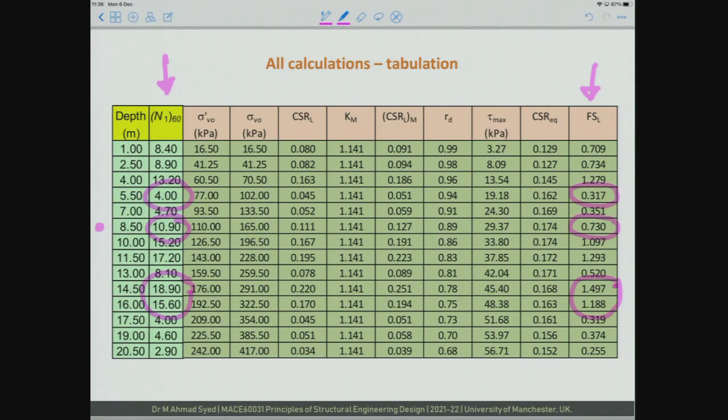So you have a higher resistance against liquefaction for relatively higher N values, and vice versa, you have relatively smaller resistance for the same earthquake when you have smaller N values. So is there some soil good for construction, but more risky at the same time?